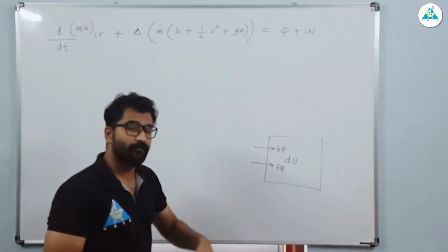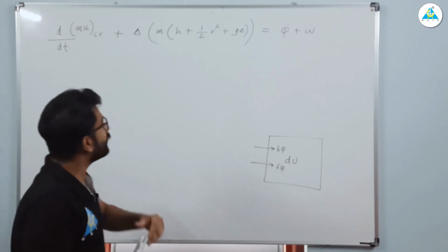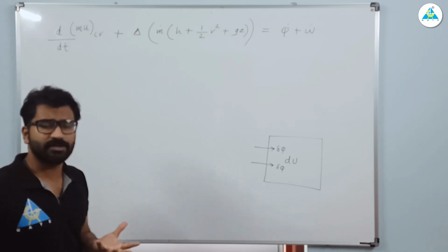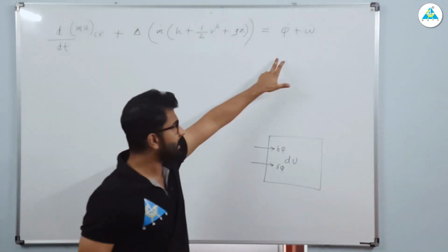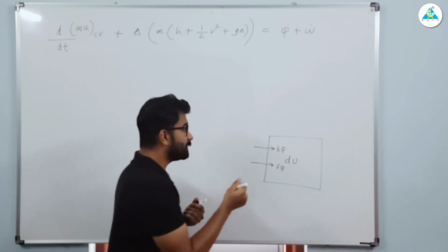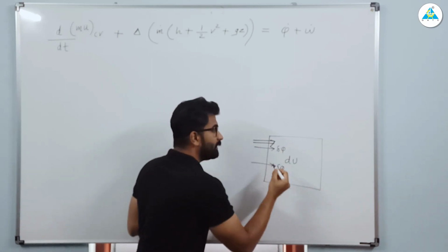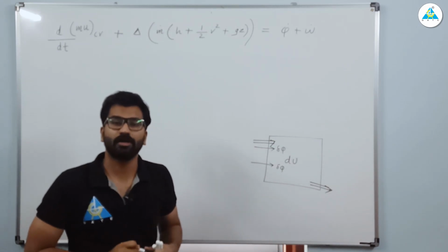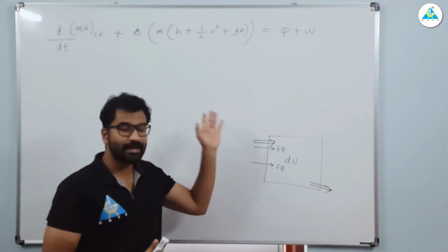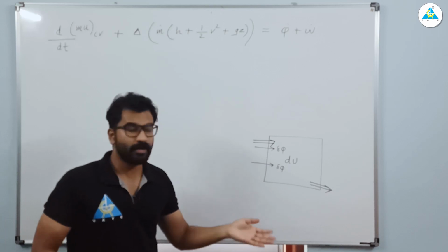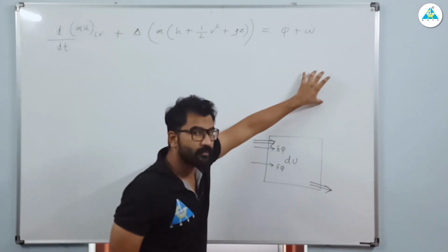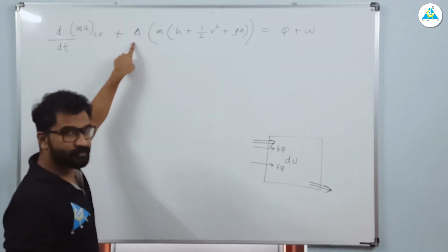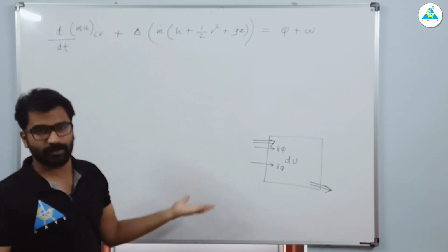If it is an open system, the internal energy change inside is again due to heat and work, and there are two more terms: the energy coming in due to mass flow in and the energy going out due to mass flow out. That is inlet minus outlet on the right hand side, which I have taken to this side, so we represent it as outlet minus inlet.